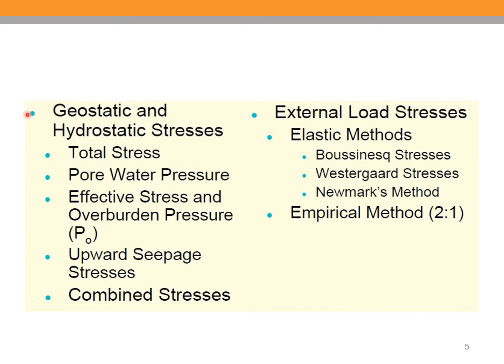When we consider the geostatic and hydrostatic stresses, you will have to deal with the total stress, pore water pressure, effective stress and overburden pressure, upward seepage stresses if there is seepage, and combined stresses. And when we consider the external load stresses, you will have to employ the elastic method. Under that you can consider the Boussinesq stresses, Westergaard stresses, or the Newmark method, or you can consider the empirical 2:1 ratio method.